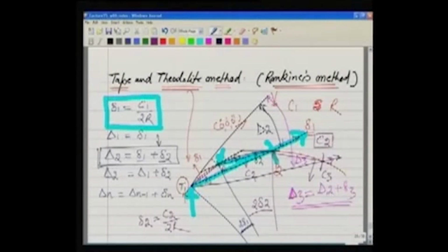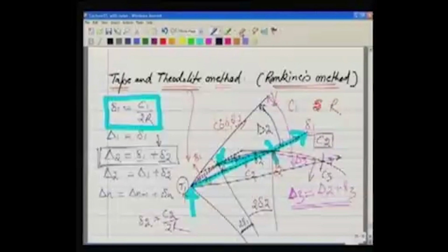So cutting that distance means, we are sighting through the theodolite. Now someone is moving there, taking an arc. The moment he is intersected, because we are sighting through the theodolite, so we are looking in one direction. Now the moment a ranging rod which is taking that arc is bisected, you will say that's the point on the curve. So this is how the points on the curve means a point here, then the next point, then the next point, and the next point, and so on will be established.